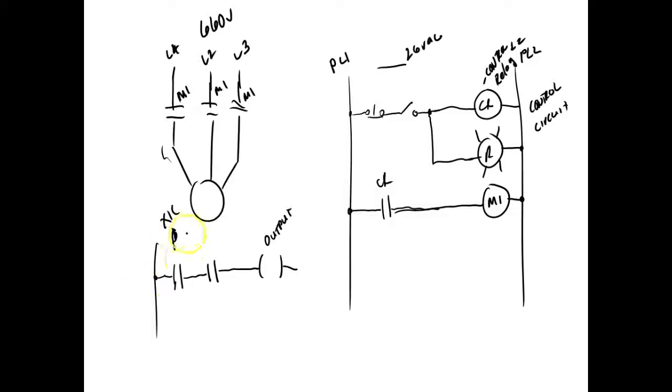So this would be one of my switches, what they call it, I don't know, PB1, I don't care. And then switch 1, okay. And this right here would be my control L2. And then I've got to assign it addresses. Then I could come down here and assign this to that output.